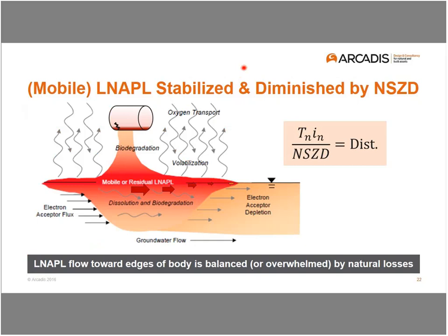So as we've smeared that LNAPL out, that also helps stabilize the LNAPL body because we're taking the mass of LNAPL that was released and spreading it over a larger vertical interval. So there's less NAPL to form a head to push that NAPL more broadly out.